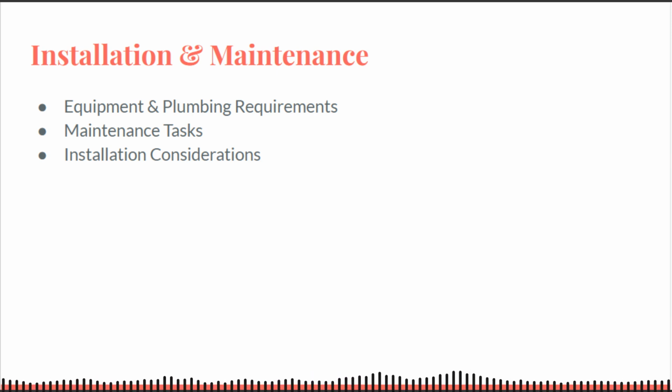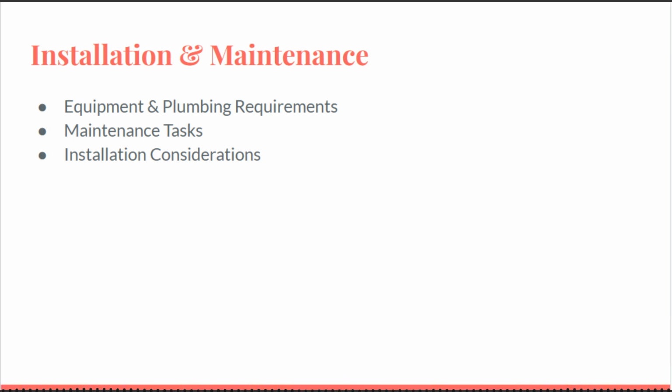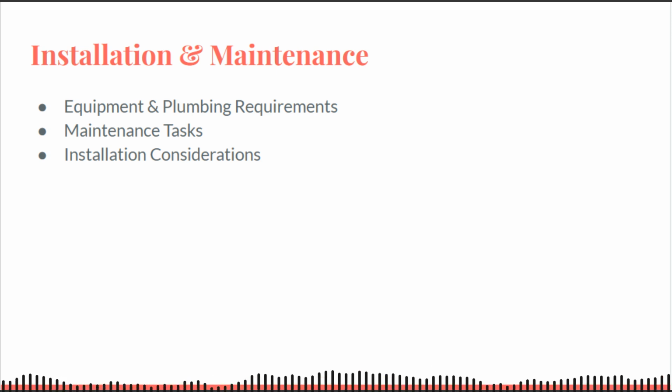Troubleshooting. Common issues include the ozone generator not powering on, check power supply or interlock, no flow through the injector, check for clogs or proper pump speed, or alarm indicators on advanced systems. A drop in ORP or rise in chloramines can also signal the ozone AOP isn't functioning fully. Many units have clear tubing or a viewing window to confirm ozone bubbles, or a glowing plasma cell or UV lamp as a quick visual check. Manufacturers like CMP provide support and parts lists, e.g. replacement ozone modules, tubing kits, UV lamps, to help resolve issues and keep the system running.